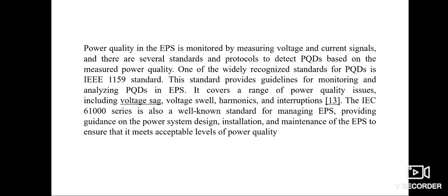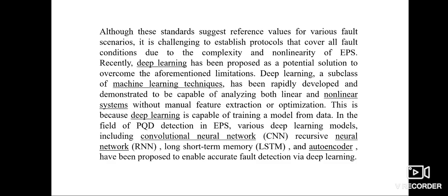swell, harmonics and interruptions. The IEC 61000 series is also a well-known standard for managing EPS, providing guidelines on the power system design, installation and maintenance of the EPS to ensure that it meets an acceptable level of power quality. Although these standards suggest reference values for various fault scenarios, it is challenging to establish protocols that cover all fault conditions due to the complexity and non-linearity of EPS.